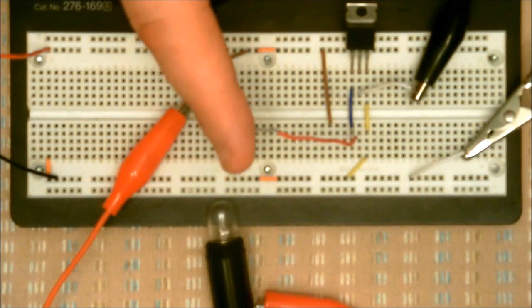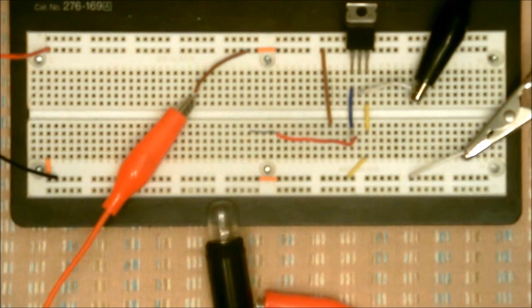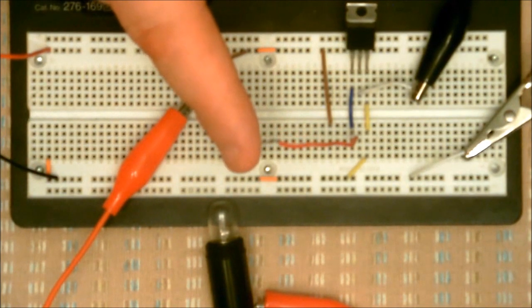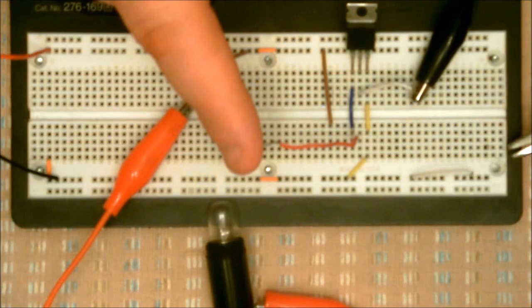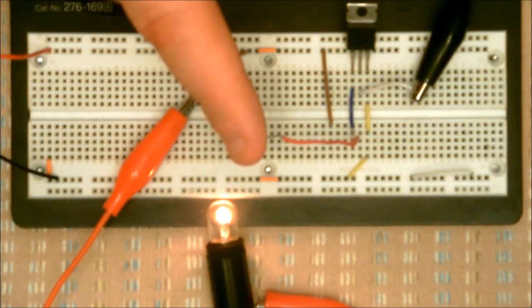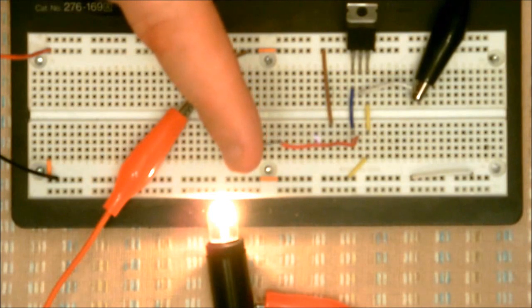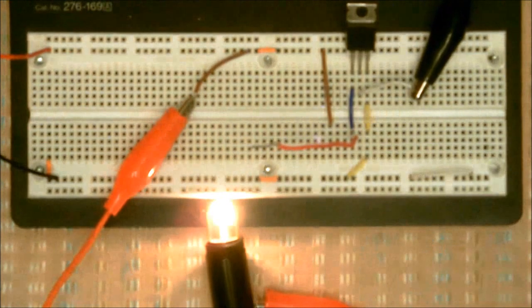Man, I could just sit here and rub the floor and still touch it. Nothing happens. I can't turn it on. But if I remove it and I can build up static electricity, look what happens. The gate turns on. This is the thing about static electricity you have to be careful with, because it can destroy the MOSFET.